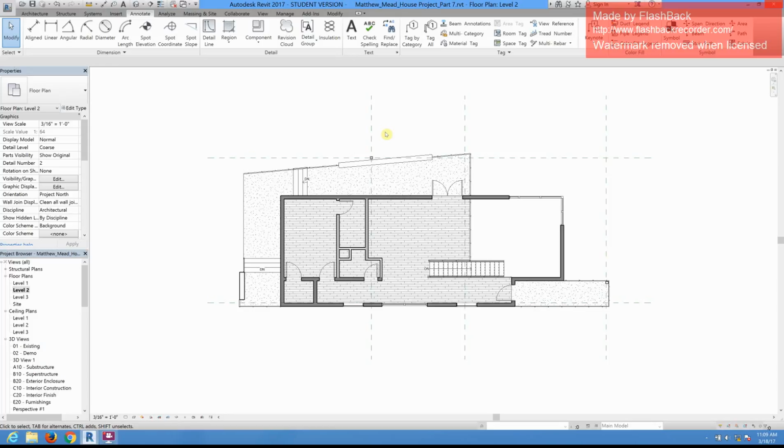So as soon as you duplicate that elevation, you just simply go and select the template, and all of those things will be hidden. Okay, you'll use these more in a professional environment if you're actually in an office, where you might have office standards. You have office standards on how your elevations look, how your floor plans look. You might have office standards for what you want your line weights to be on your cut walls, or what you want the opacity of.